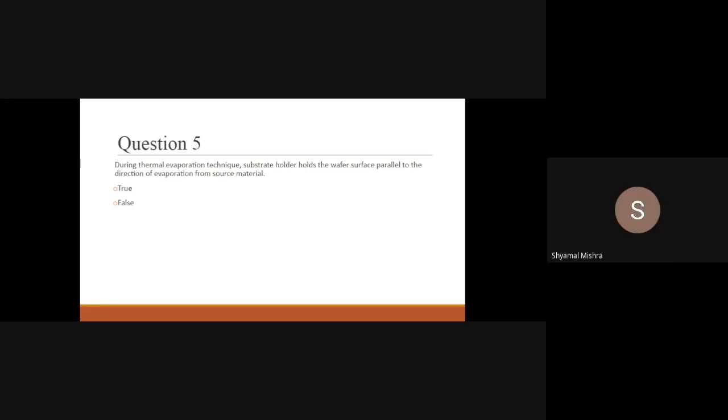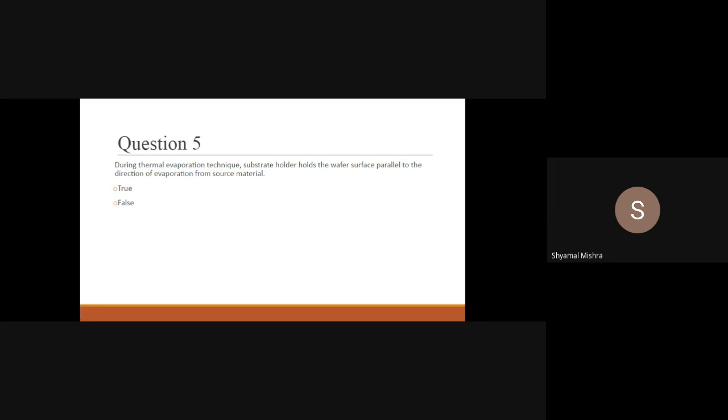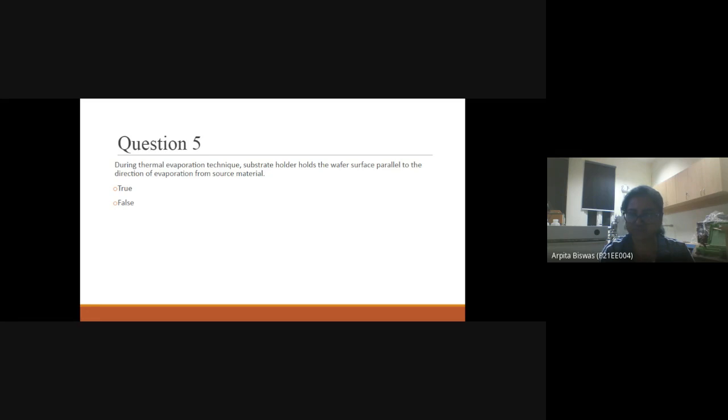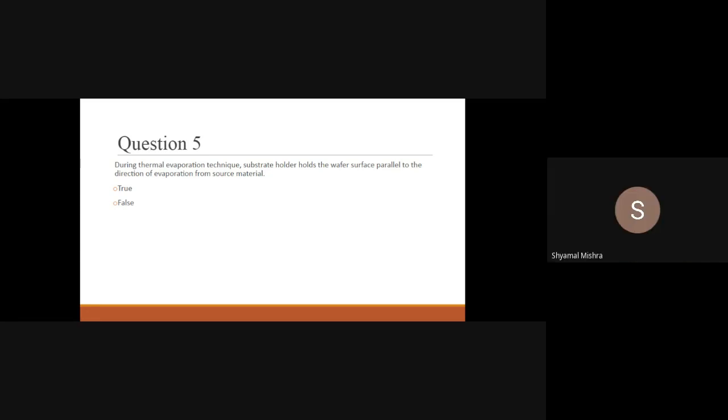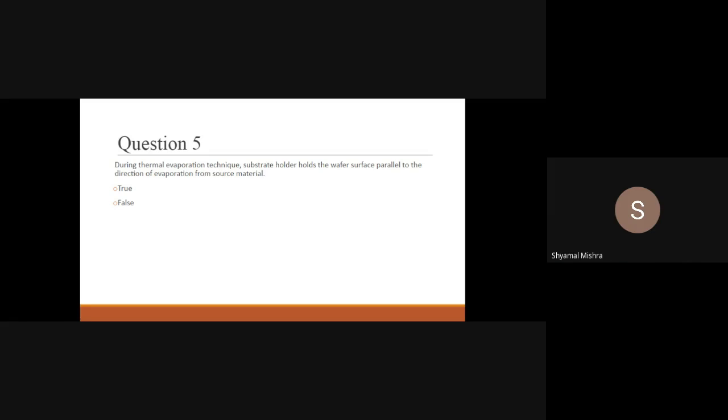Physical vapor deposition. It's a dry technique basically, where sputtering, like ions, argon, inert argon, different types of ions are sputtered on the target material, and some amount of the target is deposited on the material. And we have to maintain the process conditions also, at a certain temperature, pressure, this type of thing. So is the thermal evaporation technique a CVD or PVD technique? Thermal evaporation is a PVD technique.